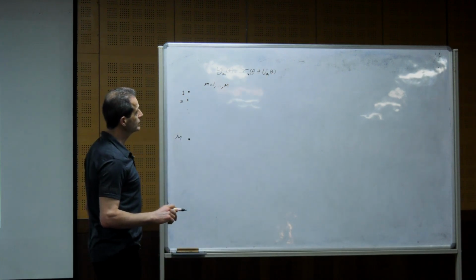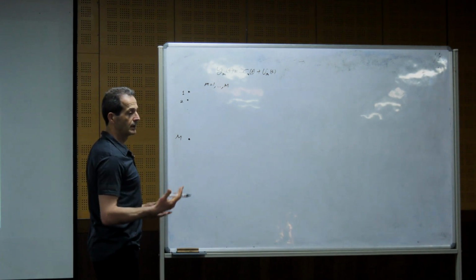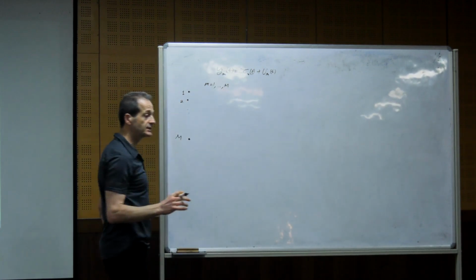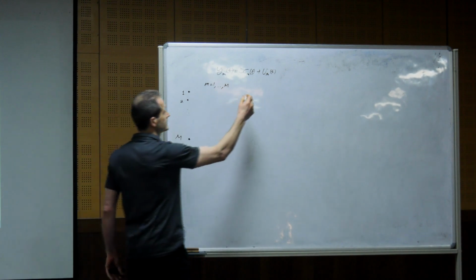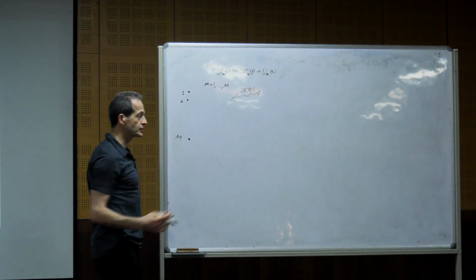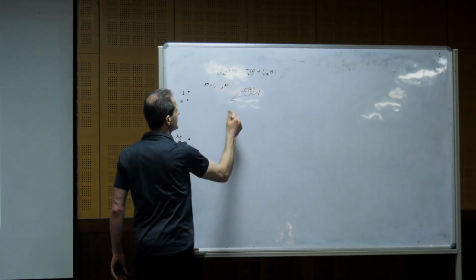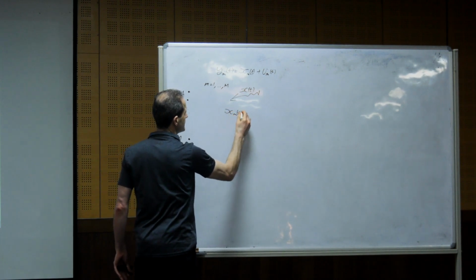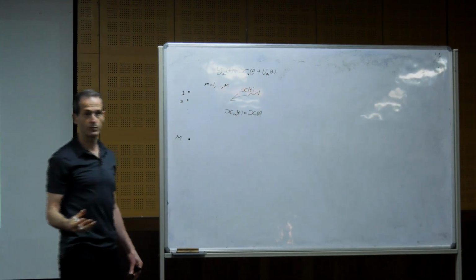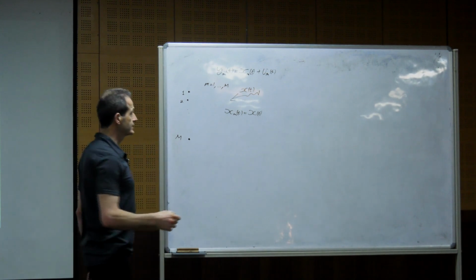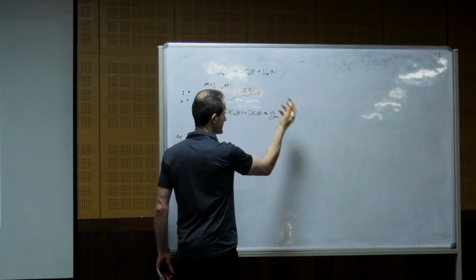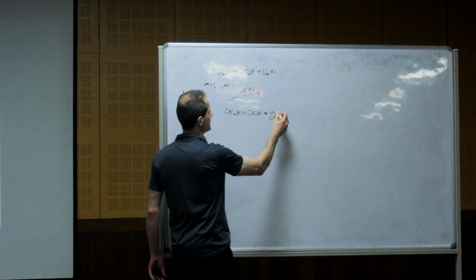So this is the desired signal that is measured in the m-th sensor, and this is the additive noise. And we also assume that we have some relation between the desired signals that are received in each sensor and the source. So the source signal x(t) propagates from a certain direction, so we can write that this x_m equals x(t), the original signal that was transmitted from the desired source, convolved with a certain impulse response from the desired source to sensor number m.